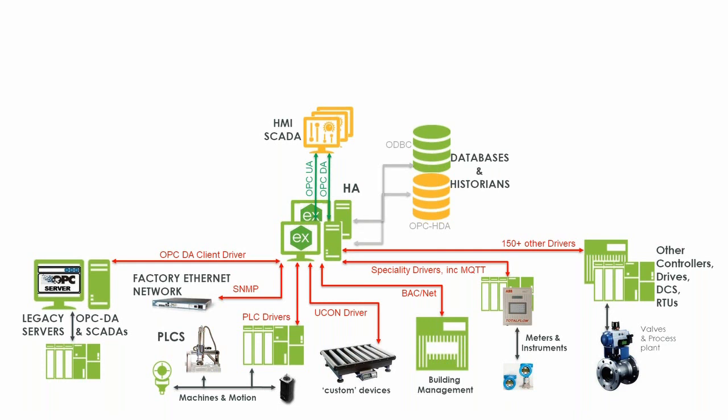We can also feed data into historians using an older protocol called OPC HDA. That is something that we can do, but the OPC HDA protocol is not particularly widely adopted or widespread. But if you need to feed data into a historian, you can do that with the KEPServer software as well.